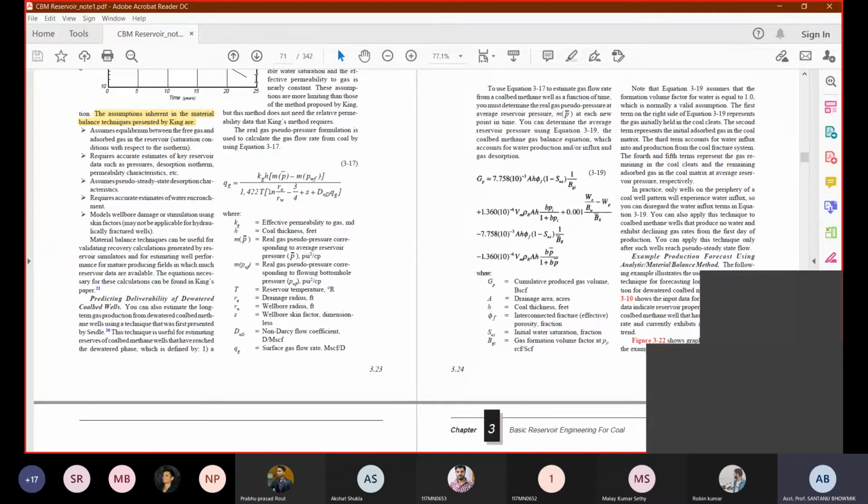Yes, sir. Okay. So this is the case for soil, where one type of water can migrate and another type of water cannot migrate, so they give extra pressure. For rock also, if there is a natural fracture system with intercepting fractures, water may percolate from one area to another area. But if the fractures are not interconnected, or there is another type of filling material inside the discontinuity aperture, then there is no place for an open channel.